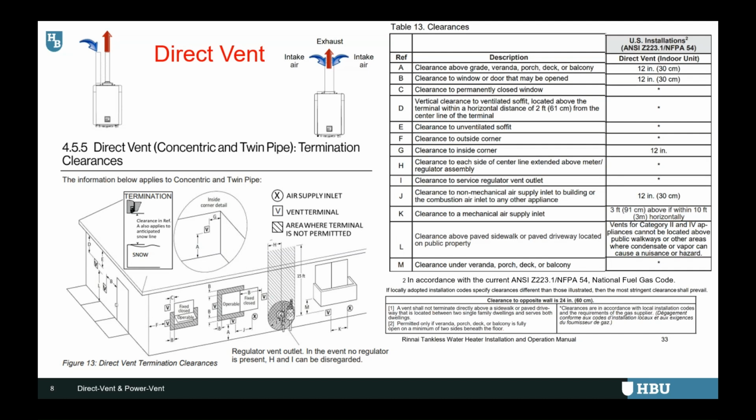And then note 1: a vent shall not terminate directly above a sidewalk or paved driveway located between two single family dwellings and serves both. And then note 2: clearances under a porch, deck, or balcony are permitted only if the area is fully open on a minimum of two sides beneath the floor. Always consult the St. Louis amendments to the 2015 International Fuel Gas Code to ensure full compliance with local regulations.